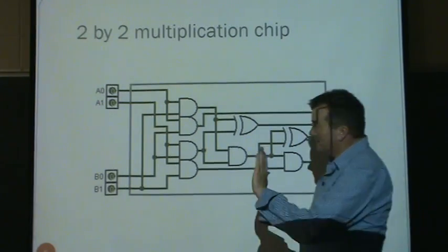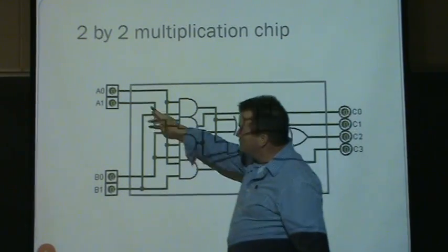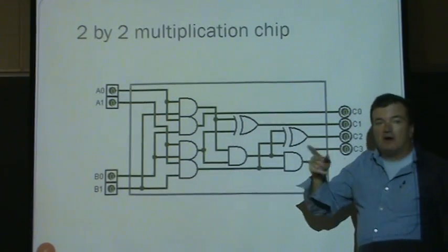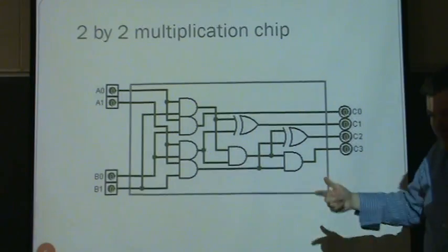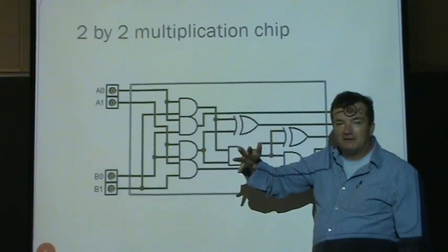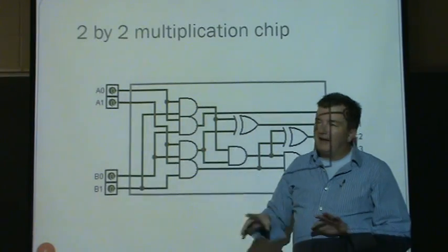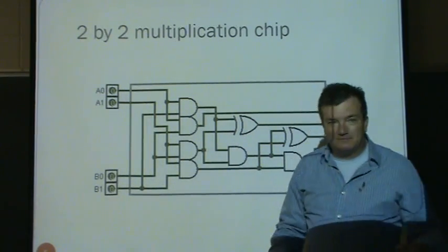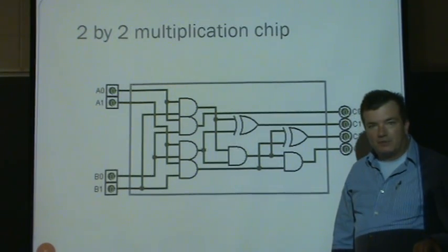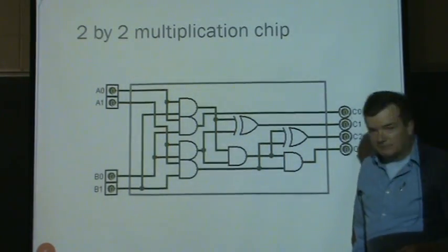Okay. So if we just did the logic on what would make the lowest bit come out, what would make this turn on? If you multiply 2 unsigned numbers together, what would cause the lowest bit to turn on? It would turn on if it was an odd number, right? Only if it's an odd number would we turn this thing on. So what would the 2 inputs have to be so that the result is odd? They would both have to be odd, right? If you multiply 2 even numbers, you get an even number. Actually, if you multiply 1 odd against 1 even that's even, right? So the only way to get an odd result would be if the 2 inputs were odd, right? So this bit, the lowest bit, and this bit would both have to be on, right?